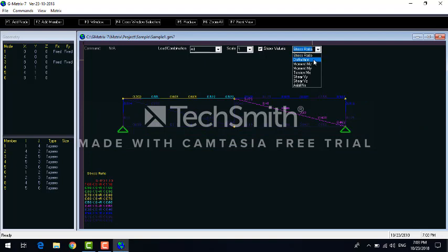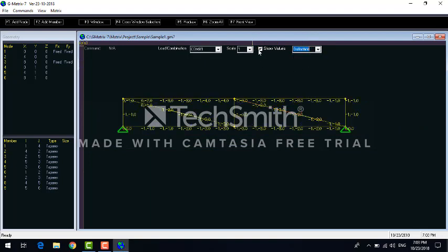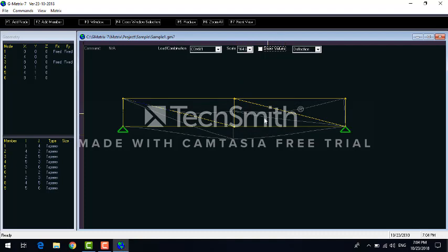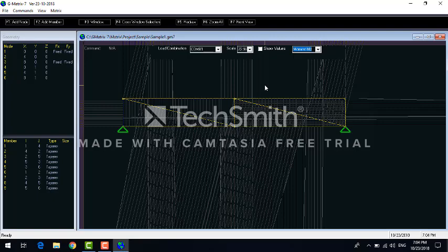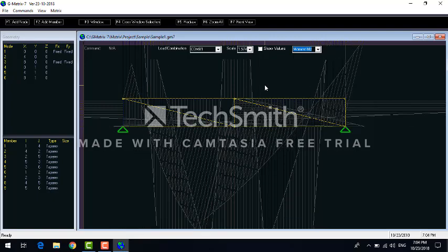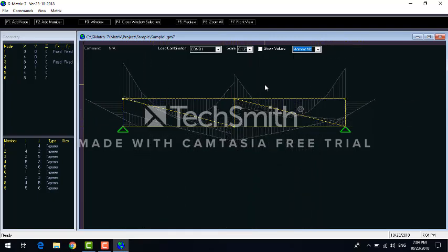In case I want to check the deflection of that structure, I can see it in number, or I can press Ctrl and turn the wheel, and the deflection will be amplified, so I can see the movement. In case I want to see the moment diagram, I mean. So this is a moment diagram.